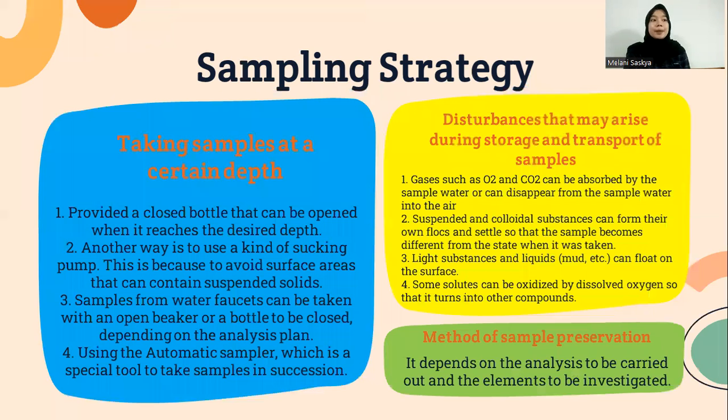Sampling strategy. The one taking a sample at a certain depth. Provide a closed bottle that can be opened when it reaches the desired depth. Another way is to use a sucking pump. Entry sample from a water outlet can be taken with an open beaker or a bottle to be closed, depending on the analysis plan. And using the automatic sampler, which is a special tool to take samples in succession.